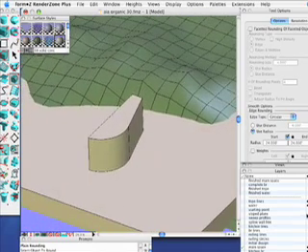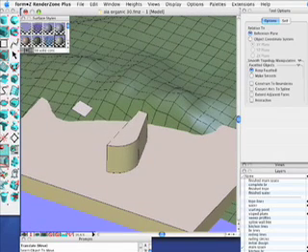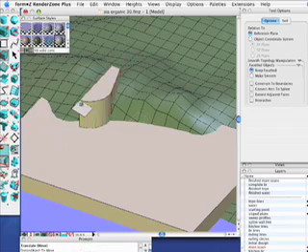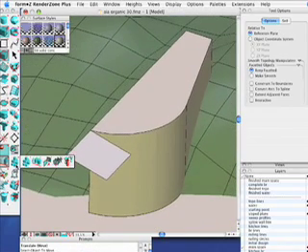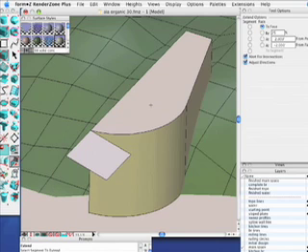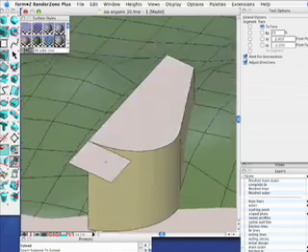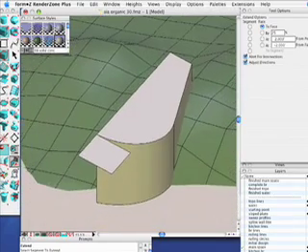One of the tools I like to use when working in architecture is the extend tool. You can use the extend tool to make one wall align to match another wall. You can use that to do the same thing for slope, so it's an easy way to create roof slope. So I can make the top face of this new object match this plane. You can see if I pan down here how they match.